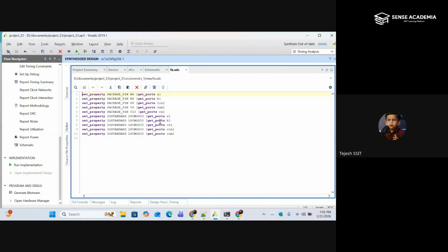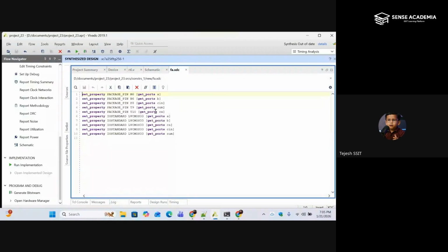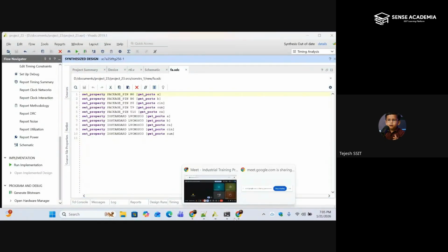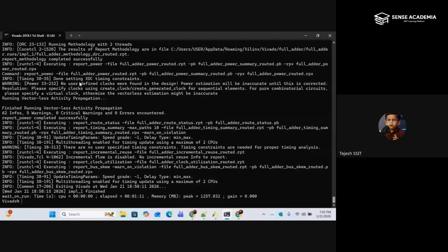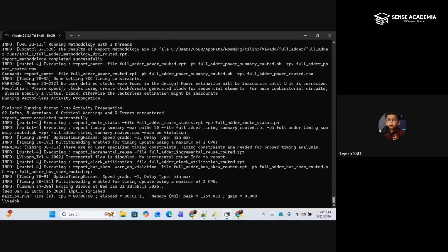Sir, we have some small doubts, sir. In the Tcl scripting, we did not connect the pins. How can we connect the pins? There is no chance to connect the pins there. You have to write this code. You have to see how we write the Verilog code and test bench code, and you can open the file and copy paste this code. You have to write this XDC code also. That is mandatory for industry persons. You have to write the XDC code, including pins and the LVCMOS33 input output standard. Okay, so you have to write the XDC code in the same manner.